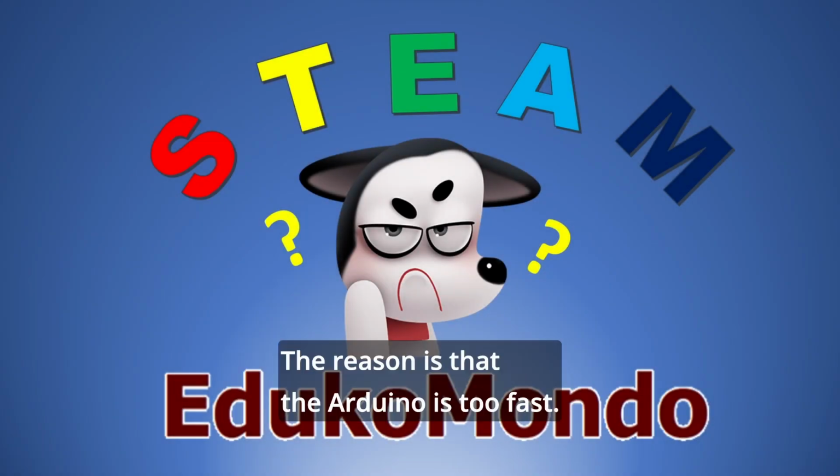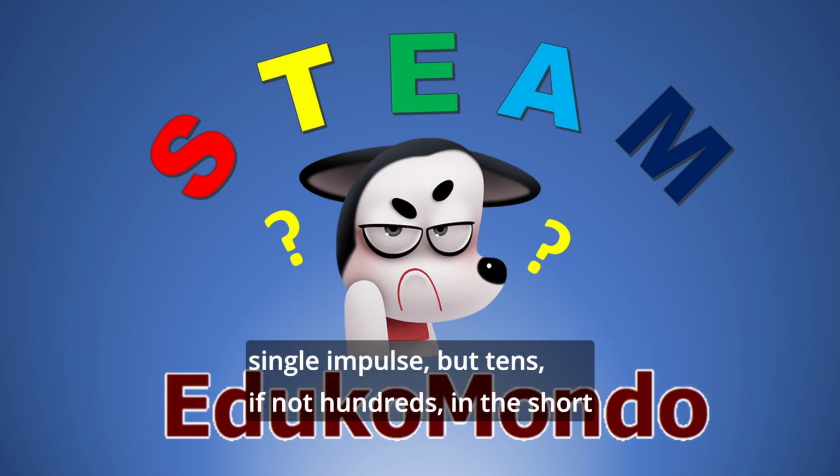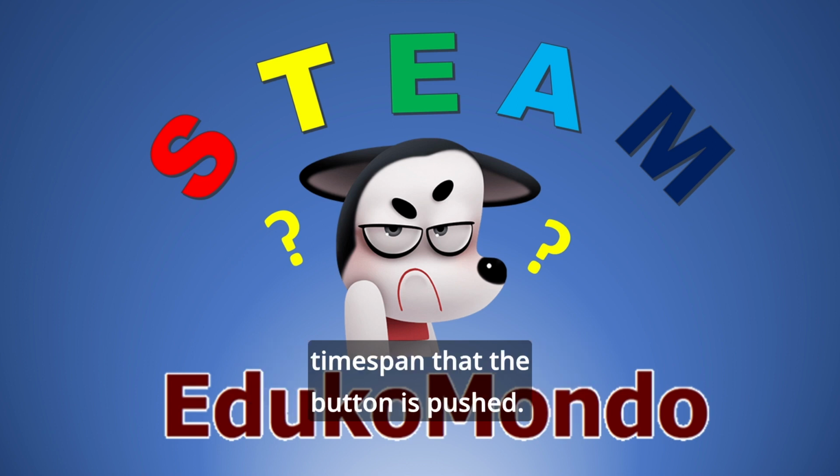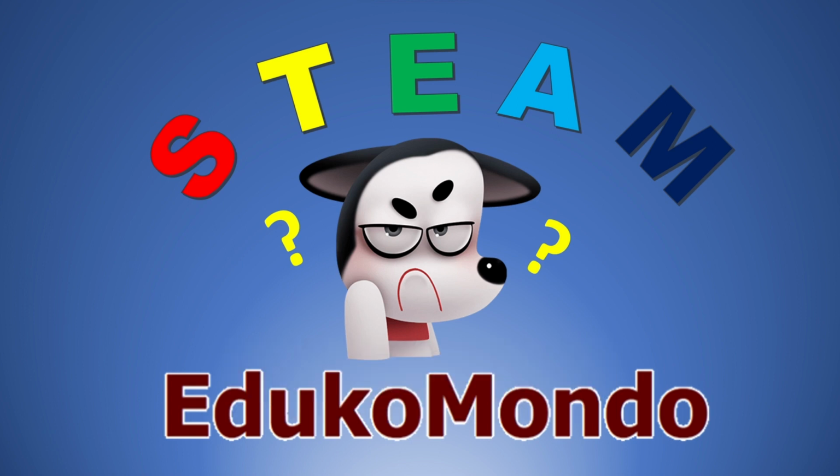The reason is that the Arduino is too fast. When we push the button, the pins A1 or A2 don't get one single impulse, but tens, if not hundreds, in the short time span that the button is pushed. The result is this seemingly random number on the display.